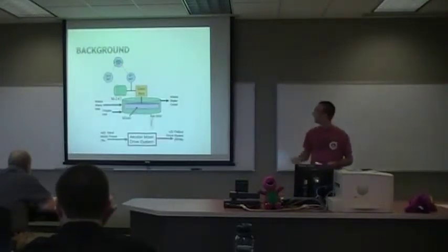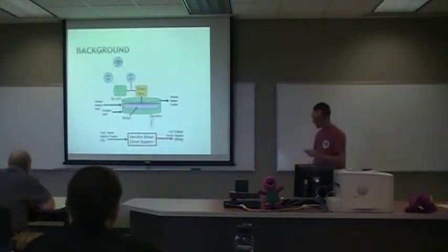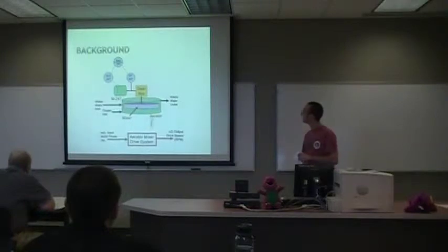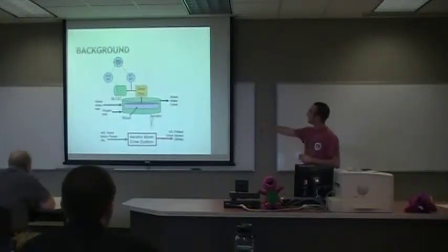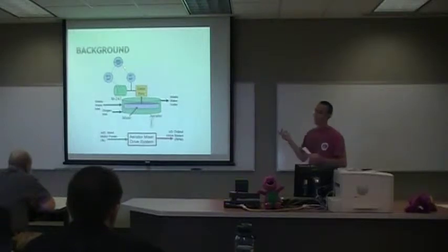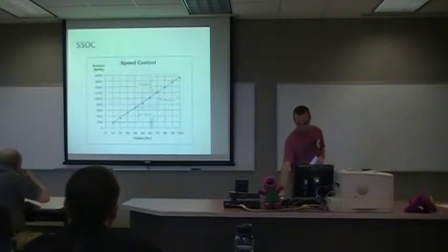A little background: this is our system. It is a feedback control system with a speed transmitter, a controller, and a speed actuator that turns the gearbox, which gives a certain speed to the mixer. And this is a block diagram of our system with the input as a percentage and output as RPMs.